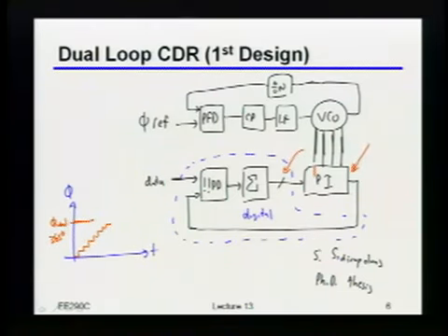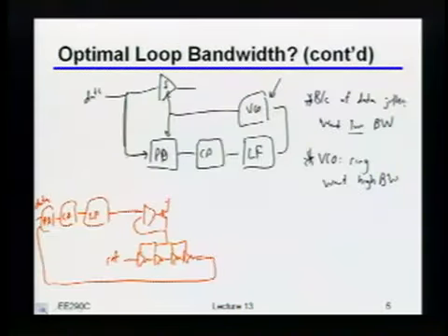Yeah? Do you even need multiple taps? I mean, it seems like you could just build a delay locked loop in that interpolator that just relies on one clock period. Okay, so you could indeed do something where, as an example, you just have a bunch of these digital delays, and then you just pick off which one of these is the right phase for you to be using. You could indeed do that. There are actually some initial implementations that did it.